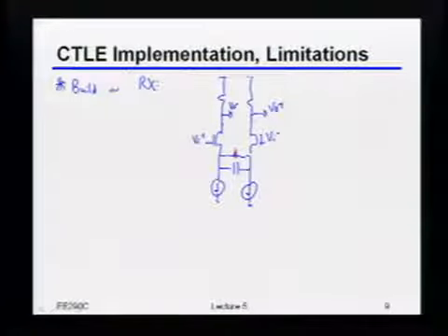So you have less gain than you might have otherwise had. Whereas at high frequencies, this capacitor kicks in and shorts the two sources together, which gives you higher gain at higher frequencies. If you remember, we were trying to build a high-pass filter, or maybe you can even call it a band-pass filter. That's exactly what we were interested in here. Again, lots of different ways you can build these equalizers, but this is the most common one, or hopefully one that you've seen a couple times before in 240.